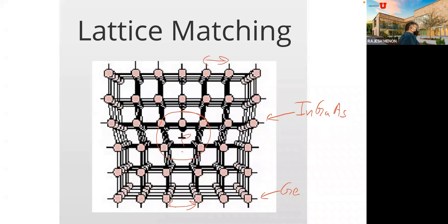Right? There's a missing lattice atom here. And that's very problematic because that inverted T-like structure there is a dangling bond. And the dangling bond means there are electronic orbitals or states within the band gap. There are defect states within the band gap into which the electrons can get trapped, and they will not reach the battery and do work. And if there are too many of those, you will get lots of electrons trapped in there, and then the efficiency of the solar cell degrades.